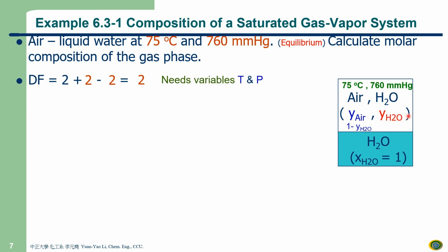How can you get this? As I just told you, this system only plays with temperature, pressure, molar fraction, and partial pressure of the water, right? So there are 4 things, and you only use 2 equations. Equation 1, Raoult's law. Equation 2, Dalton's law. That's it. The first one, Raoult's law: the things I mark in red color are the things you don't know. Once you have pressure and temperature, as I just told you, if you have temperature, you can get what? Saturated water pressure, the water partial pressure in this system, by what? Antoine equation, Clausius-Clapeyron equation, Cox chart, whatever, right? So you can get this.